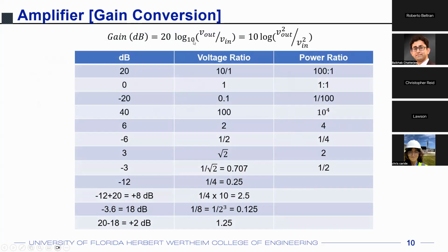However, what is the original formula of bels and decibels? What is a bel? The bel was the logarithm of your output power divided by input power. That is defined as the bel unit when you're talking about the logarithmic gain: output power over input power, and you take a logarithm to the base 10 for that. So if you're talking about power, you can represent power as V squared over R or I squared times R, as you know from your high school physics or undergraduate classes, that power is directly proportional to the square of the voltage or square of the current, right?